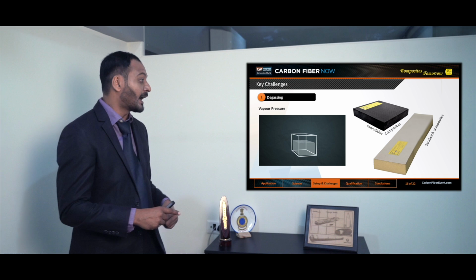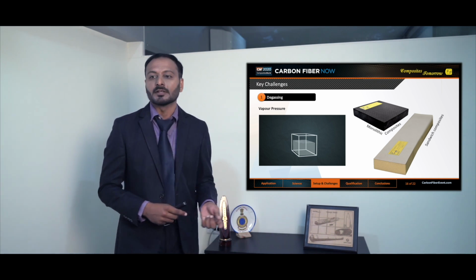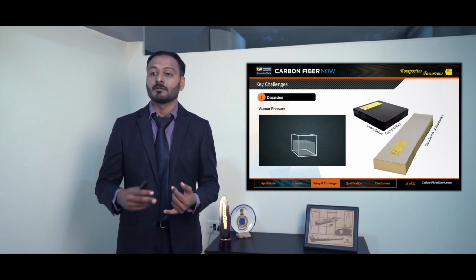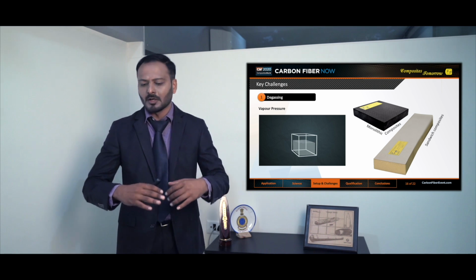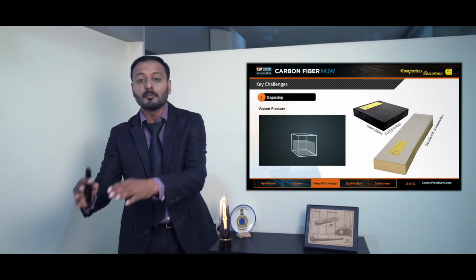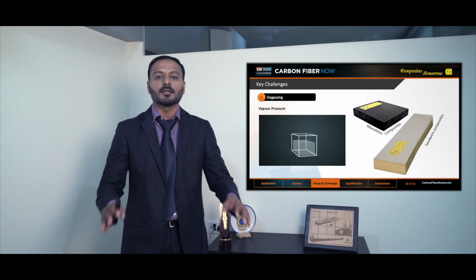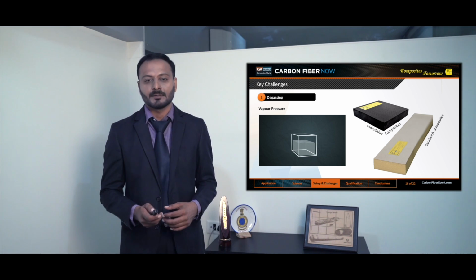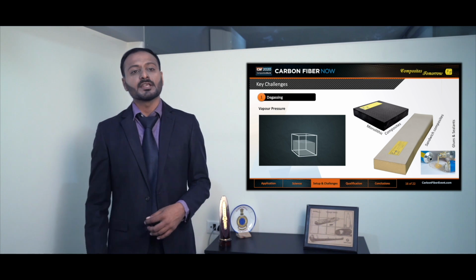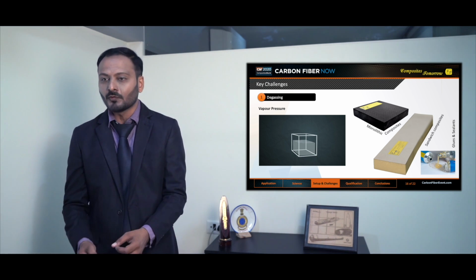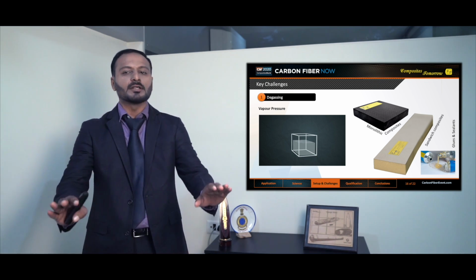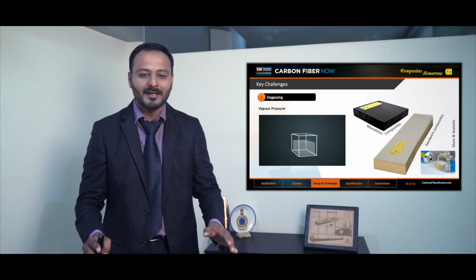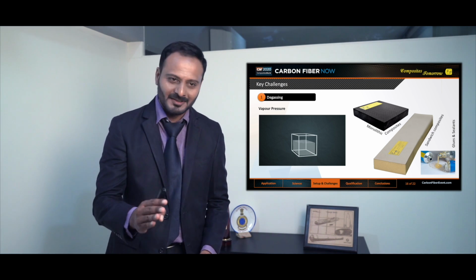This process gets multiplied with the sandwich composites because there will be either a polyurethane foam or a different variety of core, but absolutely there will be another member of plastic which will be emitting gas. And if we are using any sealants for edge sealing, glues for bonding, rest assured they are going to play their part in making your life troublesome.